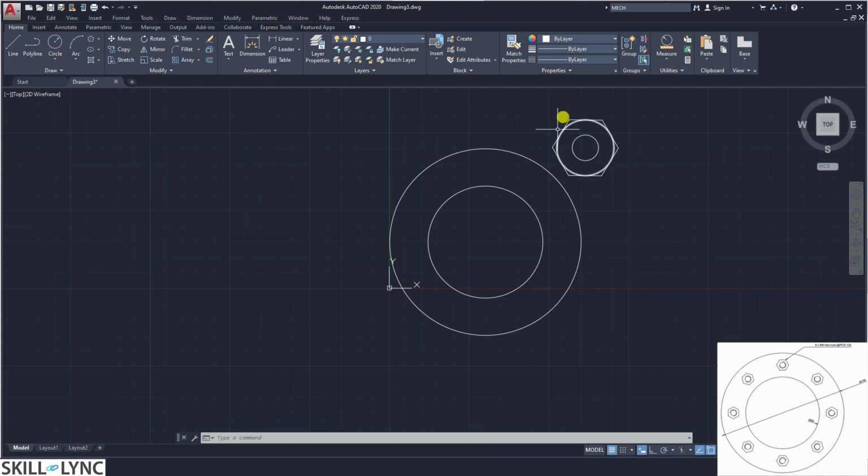So this is the representation of your hexagonal nut, and you also have to showcase the nut specification, the inner dia and outer dia, by virtue of the screw element. So the nominal dia of the nut will typically be hidden because it's the bigger one, whereas the smaller edge is what is being visible.